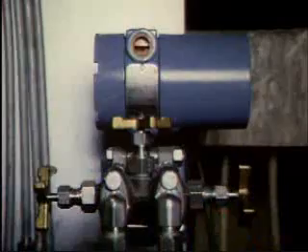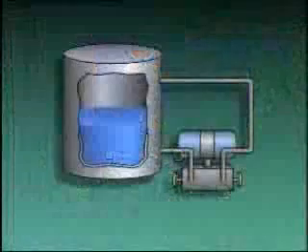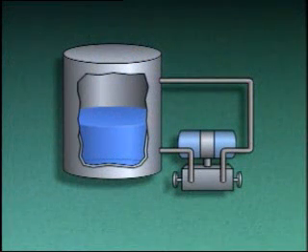Pressure gauges and bubbler systems are used in applications where the tank is not pressurized. They're not designed to measure the levels of liquids under pressure. However, if a liquid is in a pressurized tank, its level can be determined by using a differential pressure device that's sometimes called a DP cell. A DP cell, like this one, measures the difference between two related pressures.